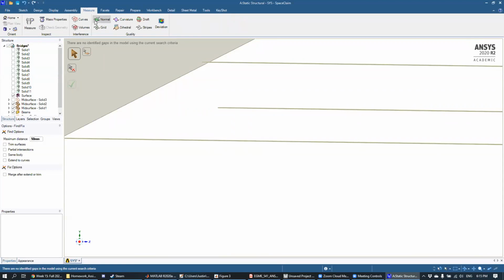So let's go ahead and click Measure. Okay. And then let's click this measuring tool right here. Okay. And so what this measuring tool allows us to do is measure certain things. Okay. And so before we do that, I'm going to turn on this option right here called Show XYZ Vectors. And what that'll do is it'll allow us to show the XYZ distances in between certain things.